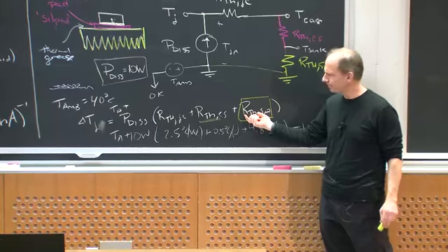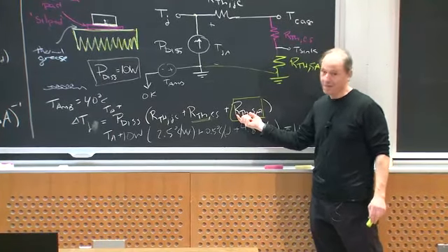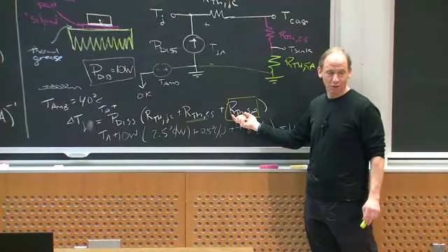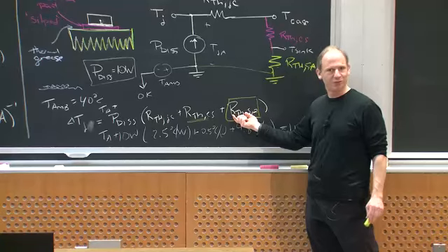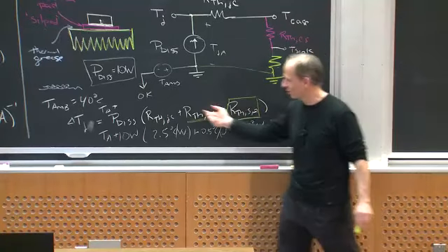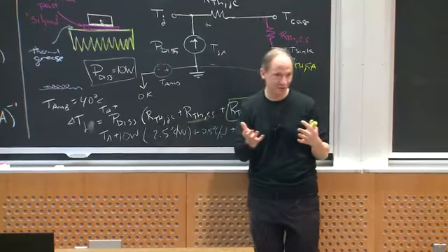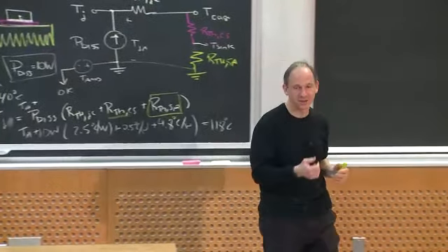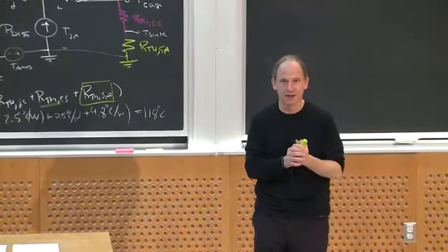Okay? What happens if you can't do it? Well, you either have to reduce your dissipation or find a better package with a lower junction to case resistance, or some other combination of things, right? And you're often pushed up against the wall, especially if you're trying to go for high power density.